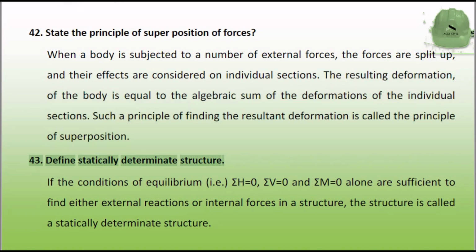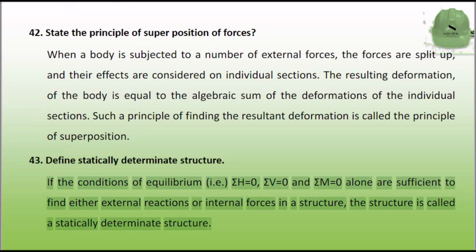Define statically determinate structure. If the conditions of equilibrium, i.e., ΣH equals 0, ΣV equals 0 and ΣM equals 0 alone are sufficient to find either external reactions or internal forces in a structure, the structure is called a statically determinate structure.